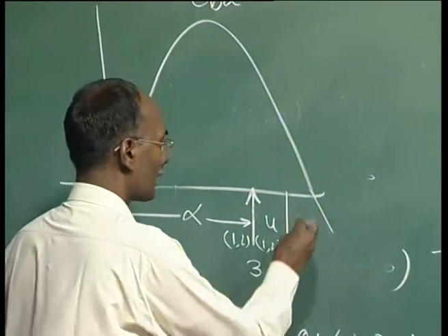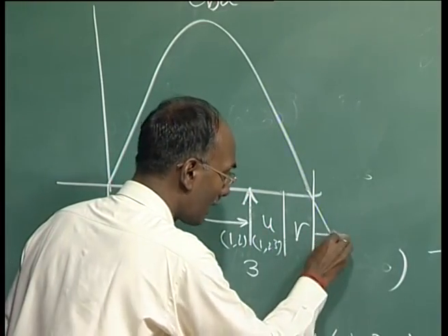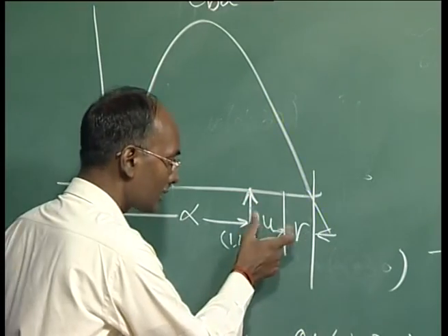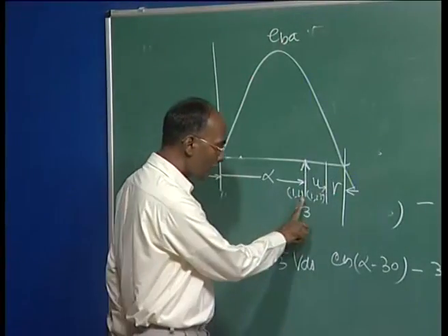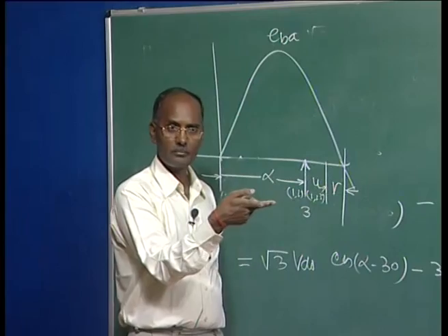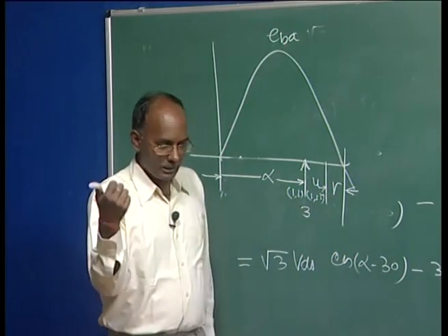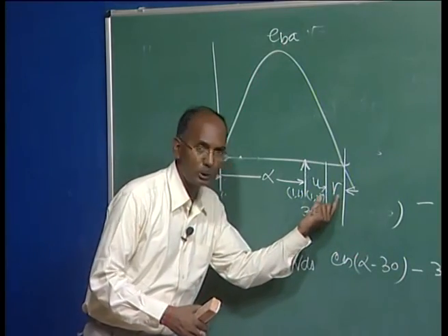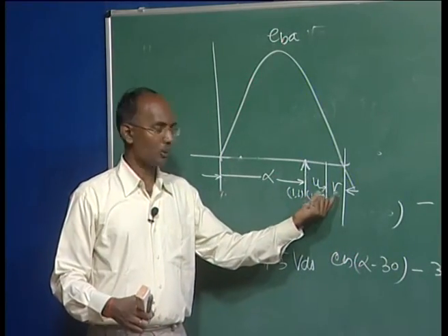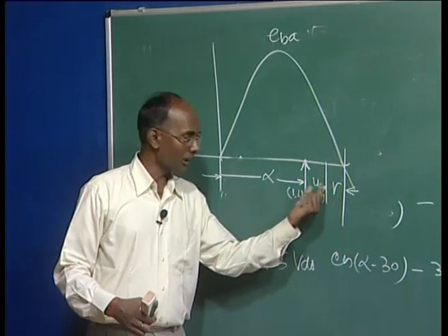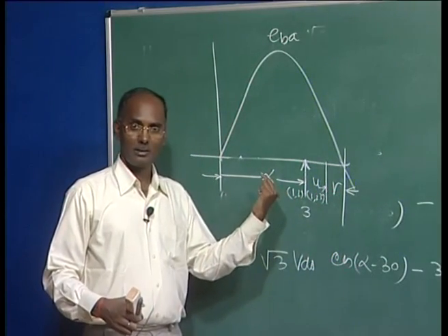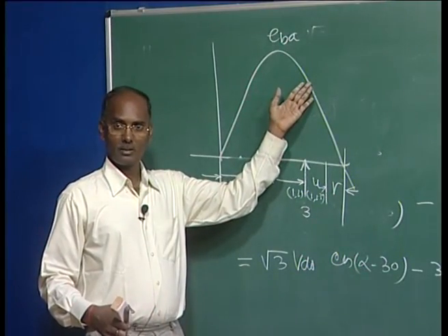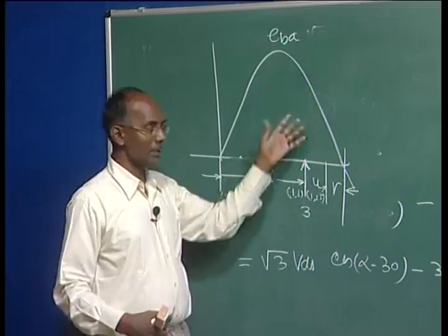That is why it is said that you should maintain this angle gamma, which I mentioned in the beginning. This is the extension angle you have to give, because this may keep on changing, since your beta is also based on some calculation. We will see in the control aspect that beta is decided by what margin you want to maintain. Suppose I want to maintain 10 degrees here, then beta is calculated accordingly. Why? Because this voltage can also change, so it may take more time. If the voltage changes, the angle will change.